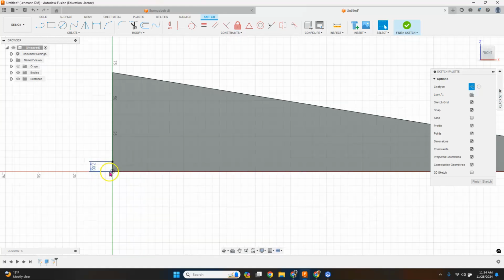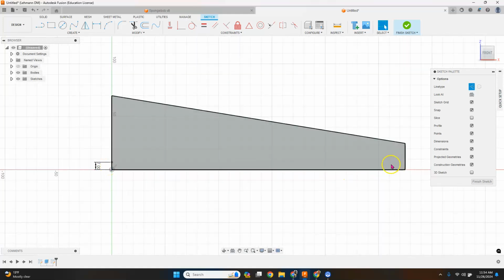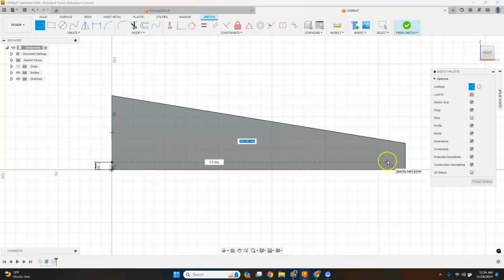Now that gives me a point, and I'm going to carry that point all the way across my car at 90 degrees. So I'm going to select that same line tool, or the letter L on my computer. I'm going to select that point and slide straight down. Make sure I'm at 0 degrees, going 90 to that edge point, so you're going straight across the block. Then select that other endpoint and click. Now we have a dotted line going all the way across our car where we can end up putting a circle on that point for our guidelines.